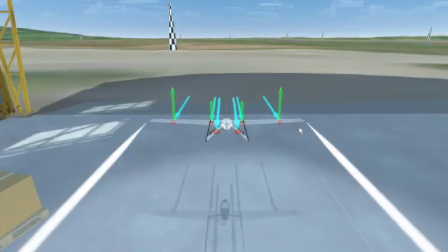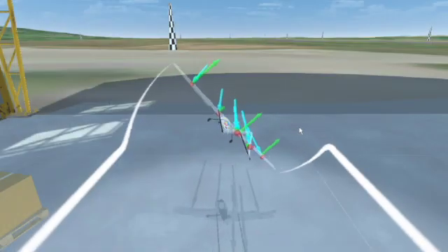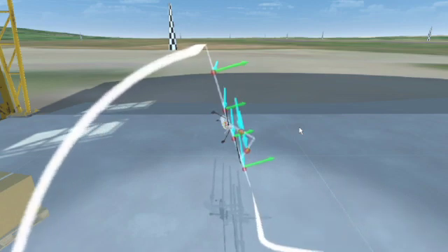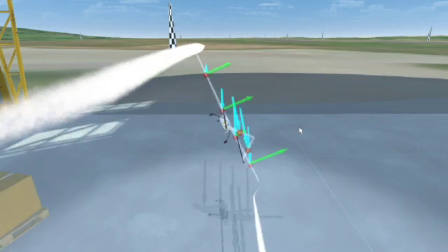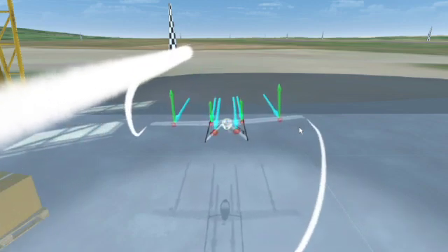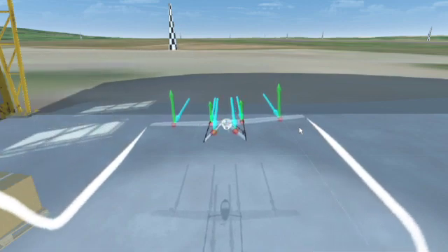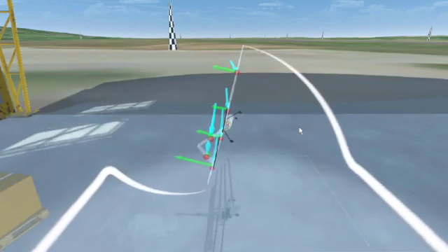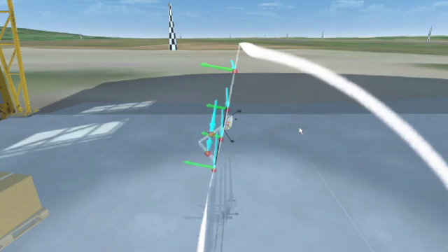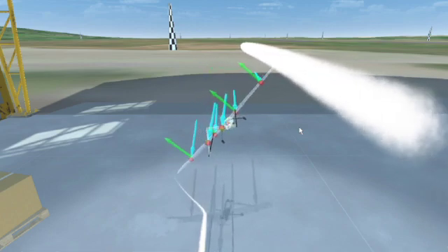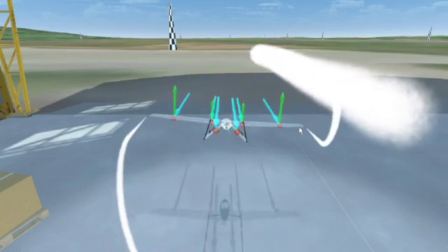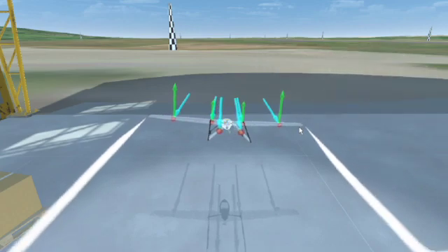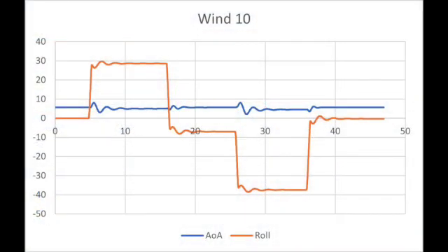A lateral stability test is conducted over a range of speeds. In order to induce rolling motion, the elevators are deflected in both directions. The values obtained from these tests are produced in the following graphs as shown, which show the effect the degree of roll has on both yaw and angle of attack. The comparison of these two wind speeds shows that at faster speeds, it takes less time to subside, which results in a less intense oscillation from the system.